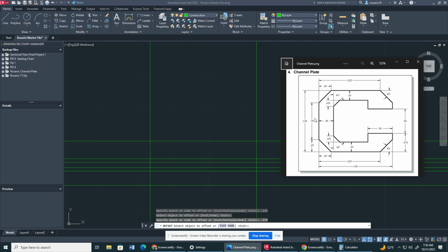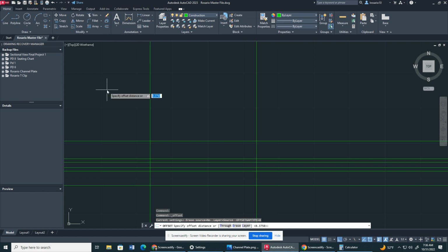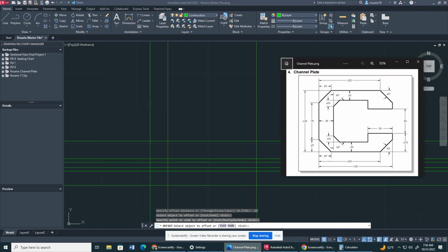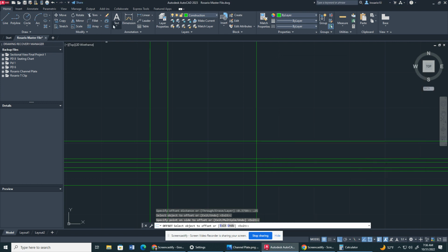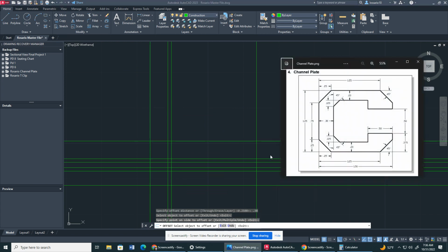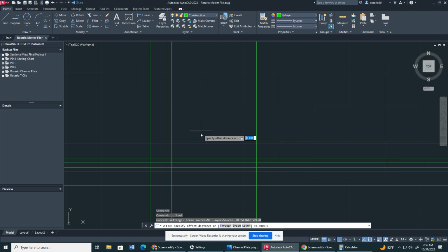So I'm going to go 0.25 first, offset, 0.25. And what's 0.25 in a fraction? Good, quarter of an inch, 1/4. Now I have to go 0.30. Remember, 0.30 is not a common fraction, so that's okay if you don't know what that is in fraction form. Now I have to go over an eighth, or 0.125. As you can see, it comes from this line right here that shows that it's 0.125. But it's going 0.125 over from the 0.30 mark.